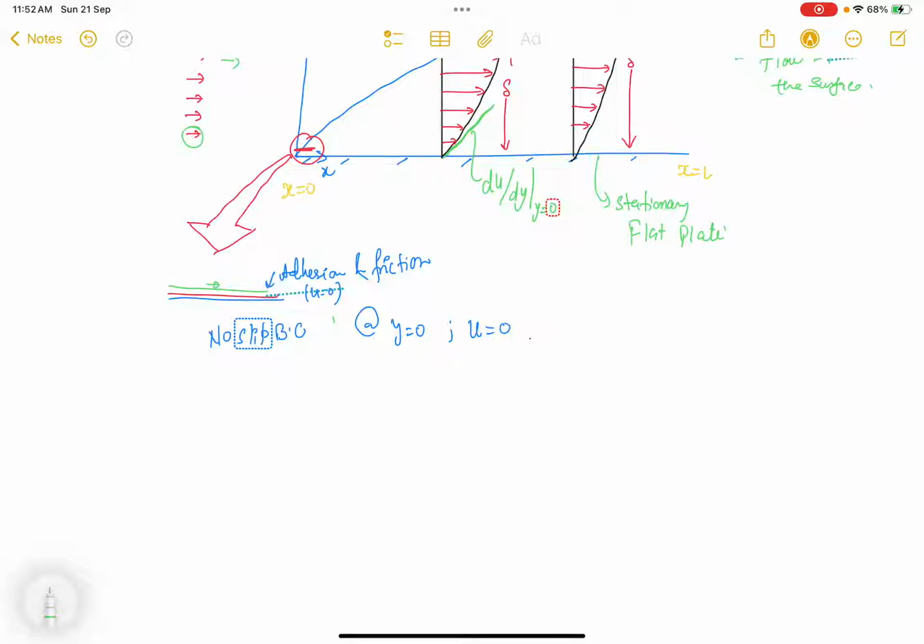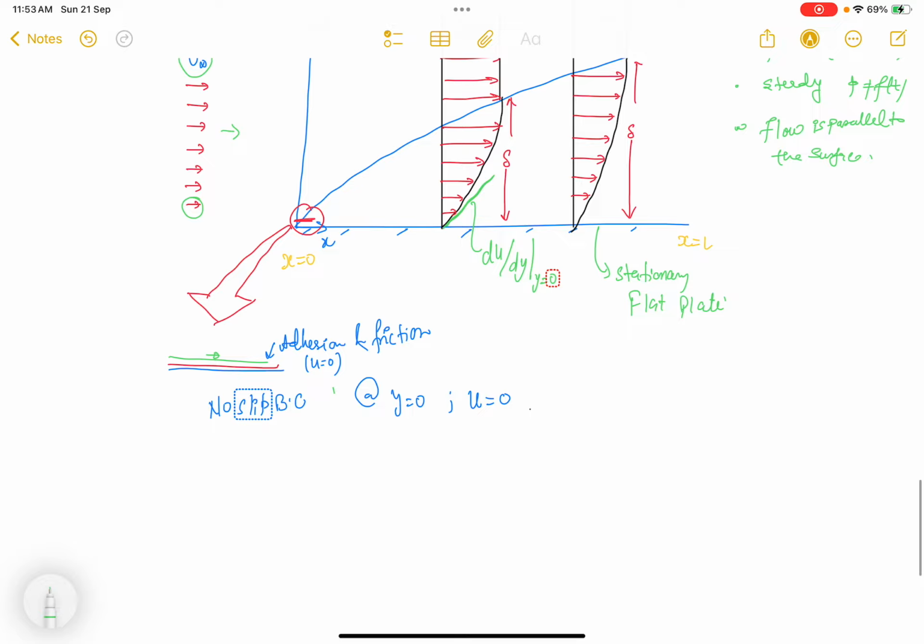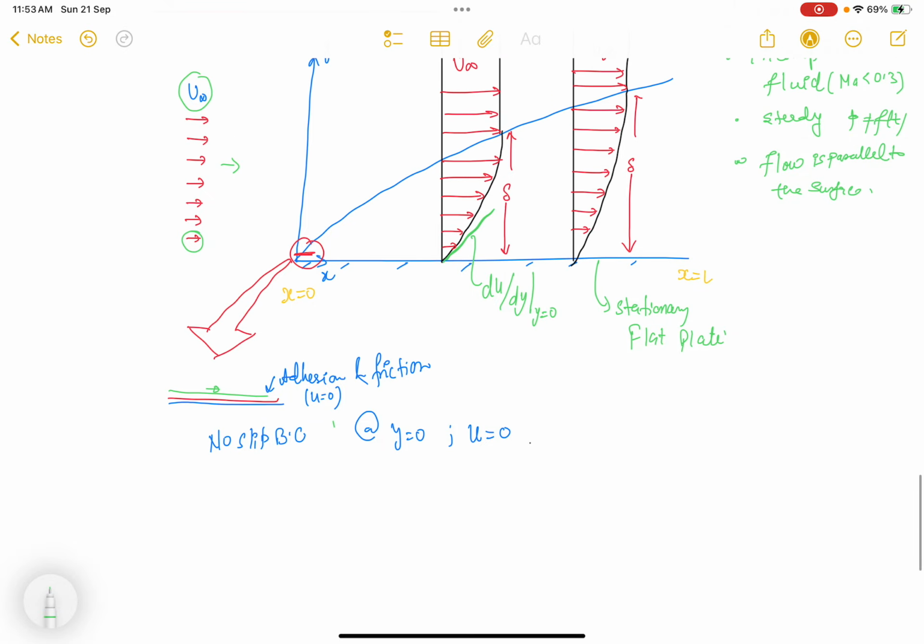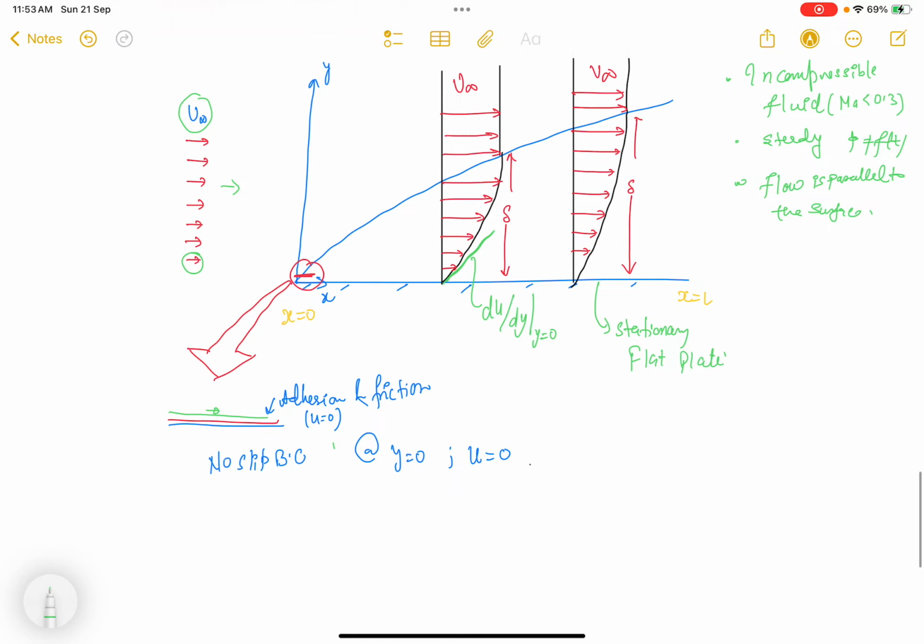As a result, friction enters into the fluid layers and the presence of the plate is felt by these adjacent layers, and fluid motion will be retarded along the length of the plate. Alright, so the distance up to which the presence of the plate is felt is known as the boundary layer thickness, right? This is a rough sense or layman language definition.